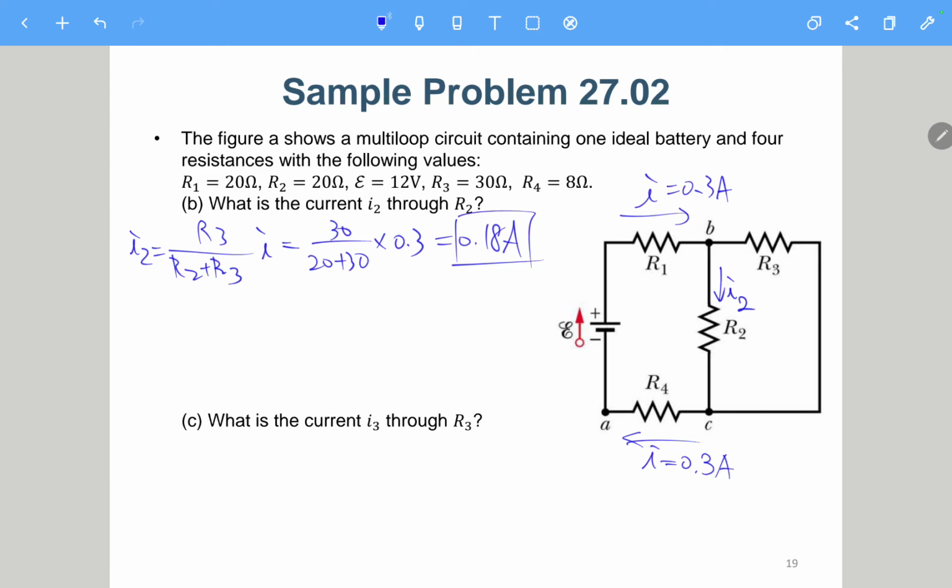Maybe you wonder why this is true, so maybe I can go through it slowly. You can determine the voltage between node B and node C, which is VBC, as I times R2 parallel R3, because just now we had the circuit like this.